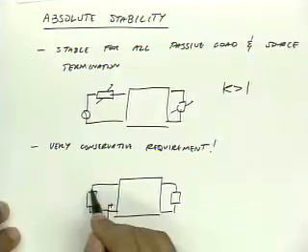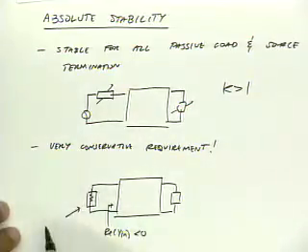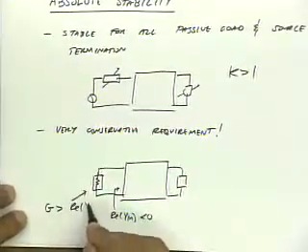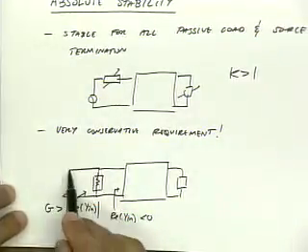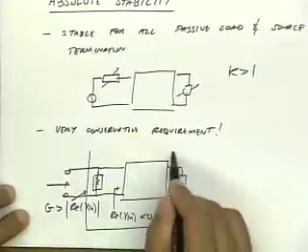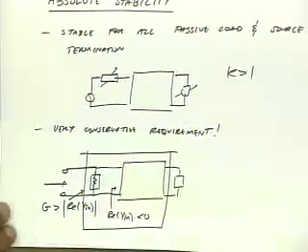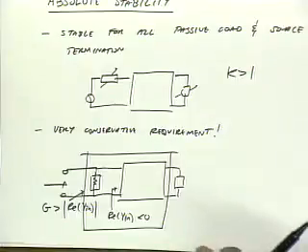If I just add a conductance, so I add here some g which is bigger than the absolute value of real part of y in, then the net conductance now looking into here is positive. So I've created a new 2-port that's unconditionally stable. Okay? And that's actually an important concept. It's going to let us define power gain for systems that are not unconditionally stable.